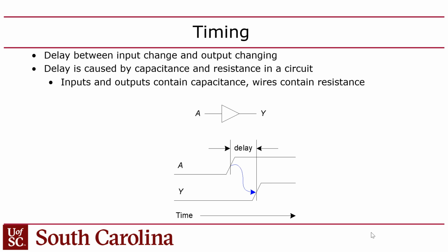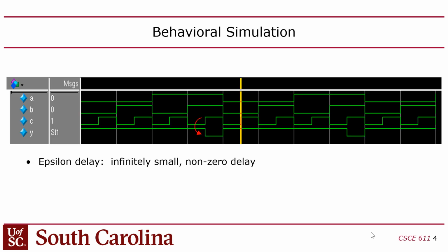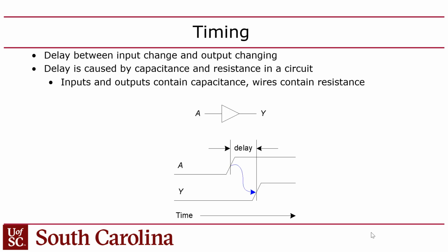Now you might say, if you look at this waveform, it looks like there's infinite slope here, like when these change, they change instantly. But on a real circuit, it takes time for transitions to happen. So when you go from 0 to 1 or 1 to 0, it takes time. That's shown here; there's a diagonal line where that change happens. When you measure propagation delay through a gate, it's measured from the midpoint of that transition. So the midpoint of the input changing to the midpoint of the corresponding output changing is the delay.